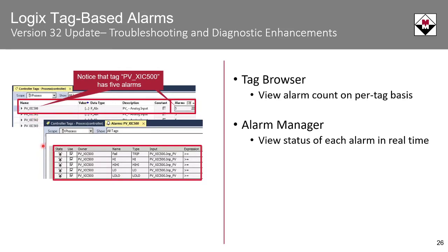The other enhancement that they made is when you go to the alarms folder under the alarm manager, they added this state column. So you can actually see the status of the alarm in real time without having to double click and look at the alarm itself.